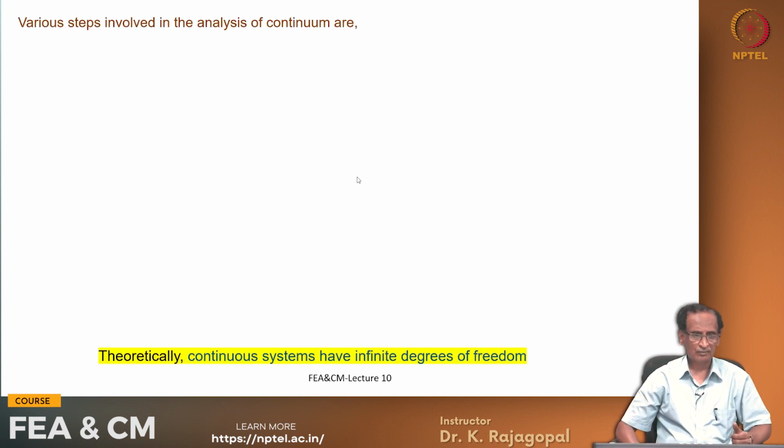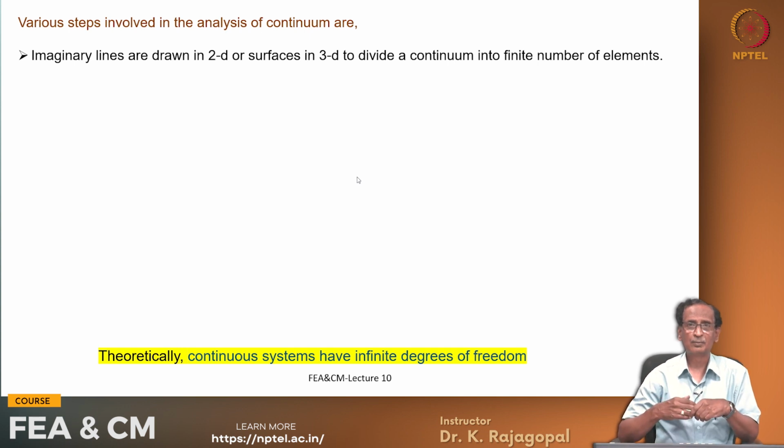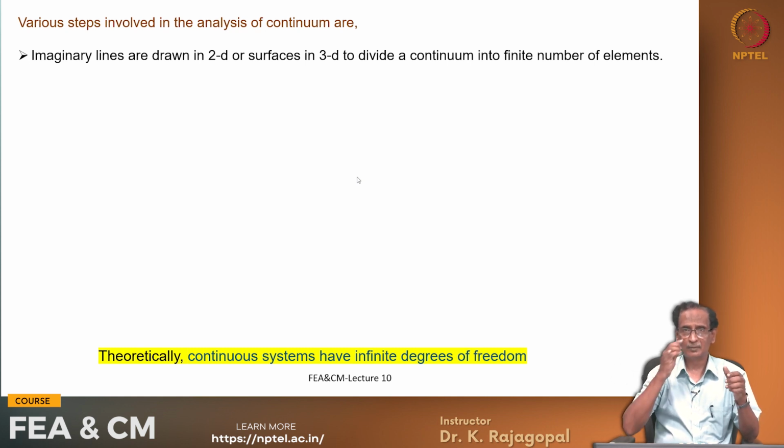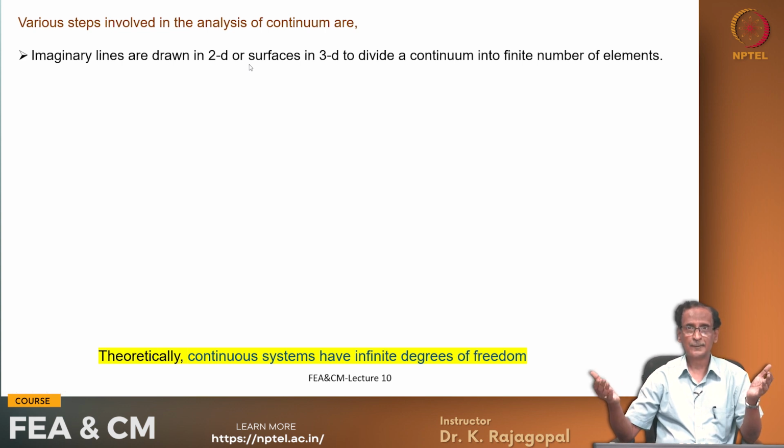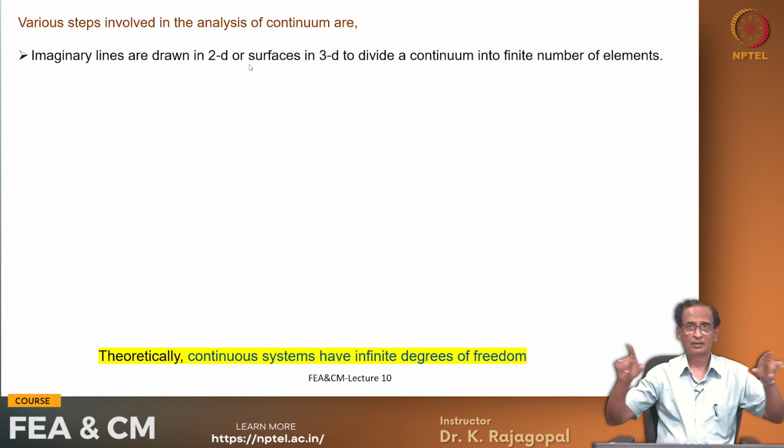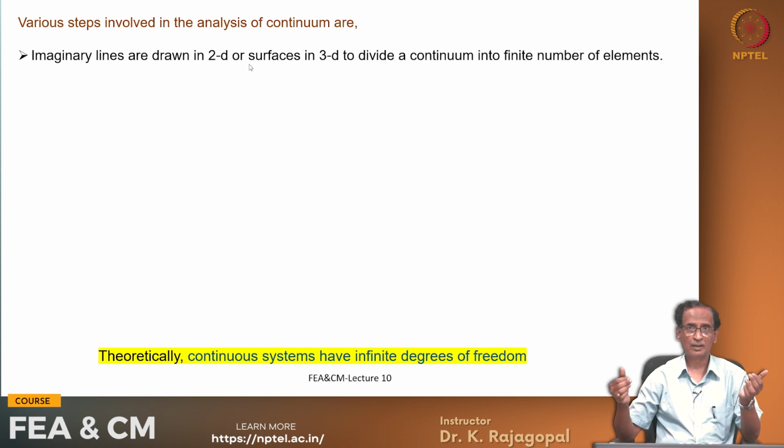And so now let us move on to the continuum, and what are the different steps. See, we are dealing with a displacement based approach, and we have seen the applications for discrete systems like the plane truss elements and then the plane frame and so on. And it is easy to imagine the number of nodes, number of elements, and then the number of degrees of freedom. But if you have a continuum, let us say you take a plate and let us say some dimensions, and how many elements are there.